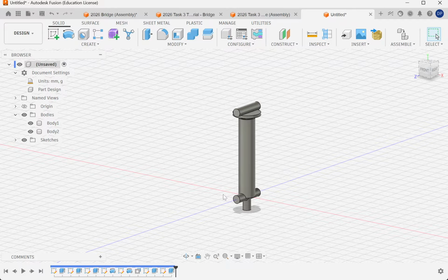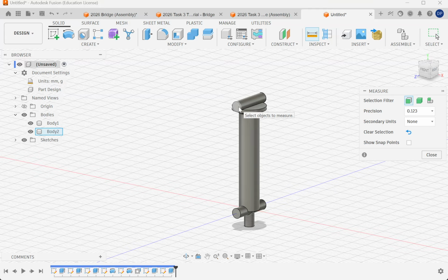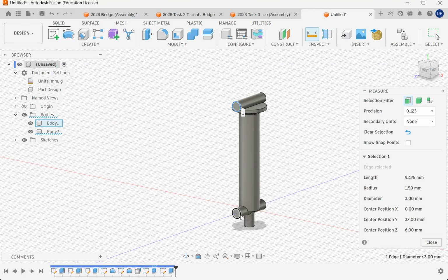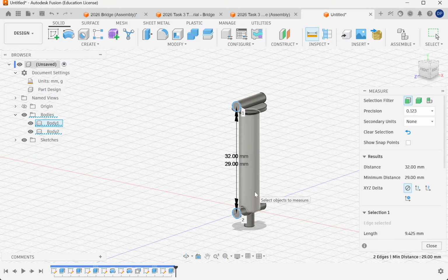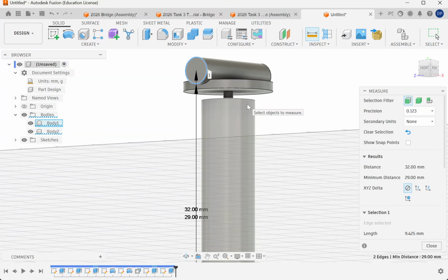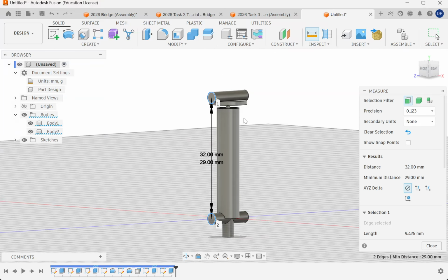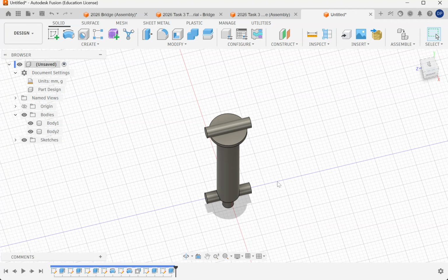Now the issue we have is we've determined the minimum height, well, we can test the minimum height. We can go to our inspect tool and we can say the distance between this circle and this circle, from the center to the center, is 32. Oh, it's slightly too large, but 31.8. I think I made a little bit of extra space. I can just shrink it slightly more. I can make them compact into each other. It should be fine.